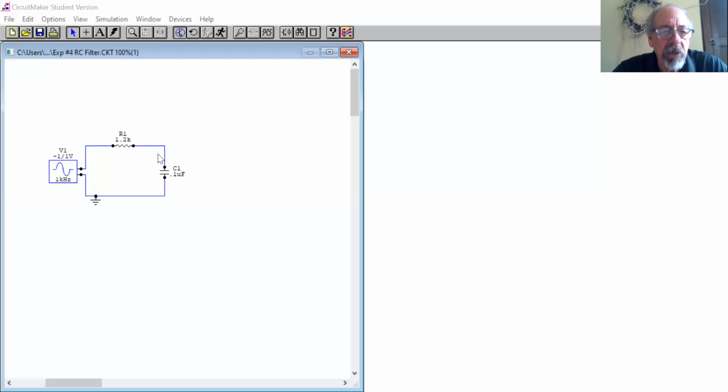So the series circuit uses standard circuit parameters, or how we deal with circuits when we try to solve them. It's a voltage divider. I have a 1.2 k ohm resistor here. When the reactance of the capacitor is very large, close to infinity, the vast majority of the output will occur across this capacitor, or you might even consider this an open circuit, and whatever you apply will appear in the output.